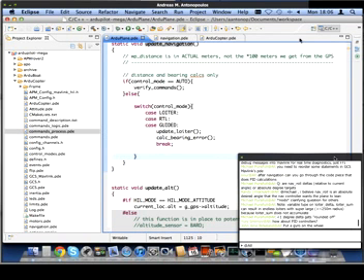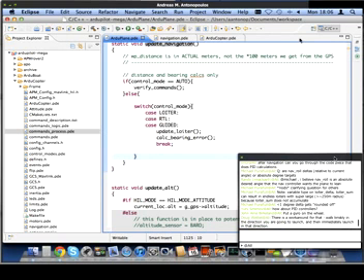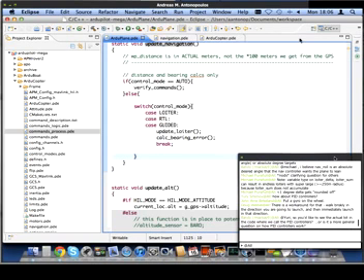So the way it works is when you enter a takeoff command, it will raise the throttle and try to use either the rudder or the ailerons to steer the plane along the current course until it reaches a minimum takeoff altitude that is specified in the mission command. Once it's reached that takeoff altitude, it considers the takeoff completed and moves on to the next item in the mission. This works particularly well with, say, catapult launches or hand-launched planes.